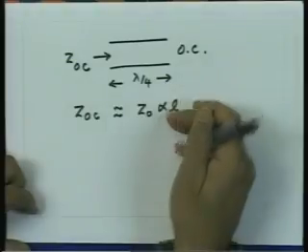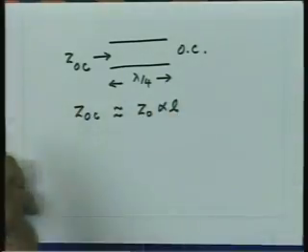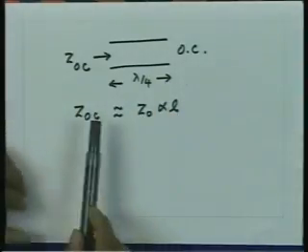Once you get this, I can use this information: if I vary the frequency around the resonant frequency, how this impedance changes. From there I can get the impedance variation as a function of frequency, or what is called the frequency response of your circuit, and from there I can calculate the quality factor of the circuit.